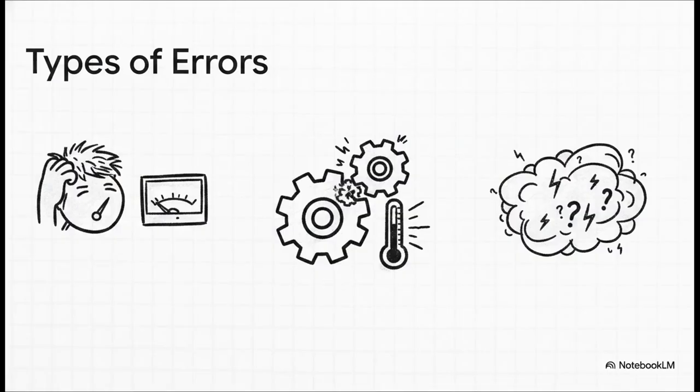So what's actually causing all these inaccuracies? Well, we can break them down into three main villains. First up, we've got gross errors. Basically, these are human blunders, reading the dial wrong or setting the whole thing up incorrectly. It happens to the best of us. Second, systematic errors. Now, these are baked right into the system itself. They can be anything from mechanical friction inside the instrument to environmental factors like a sudden temperature drop to even observer habits like parallax error. And finally, the third villain, random errors. These are those elusive, unknown accumulations of tiny effects that literally require statistical analysis to even figure out.